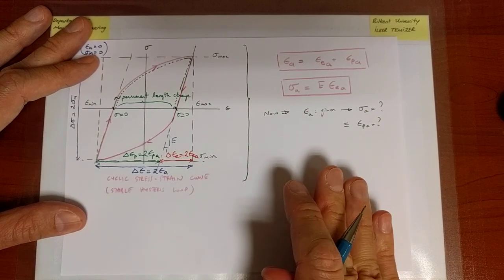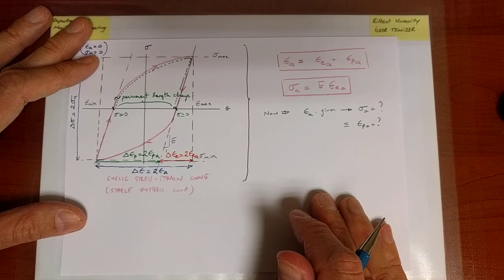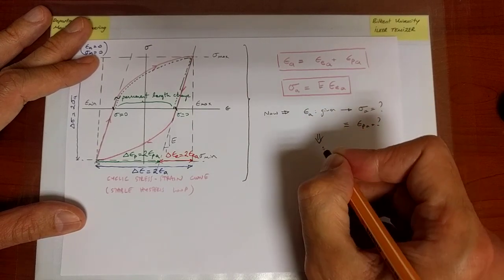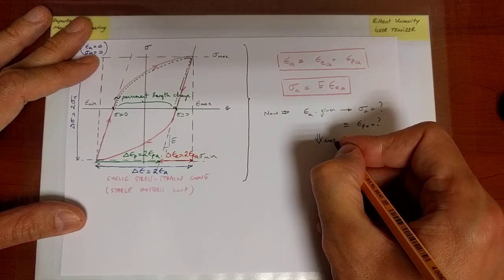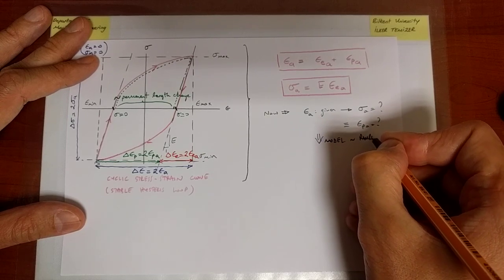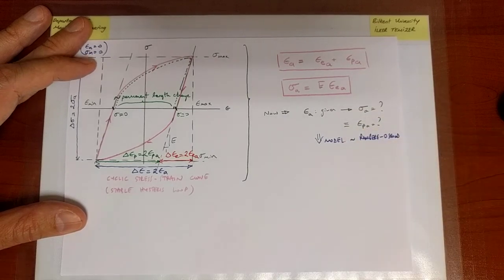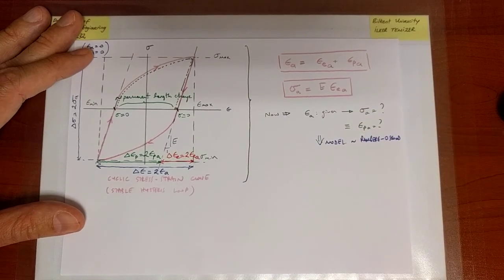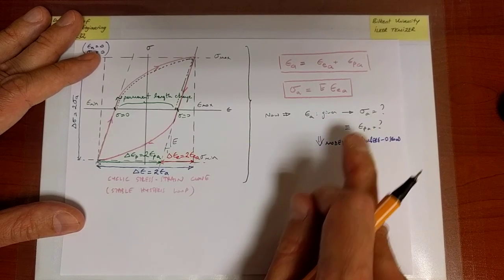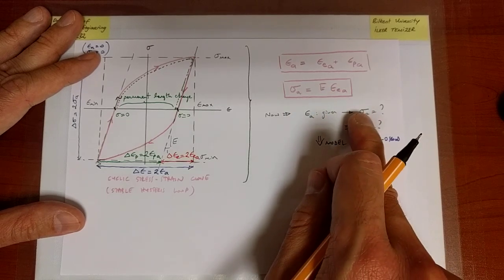And that's exactly the type of equation that we asked earlier in the context of the modeling of the stress strain curve. And in fact, we're going to now, as you will notice, follow an approach that is very similar to the Ramberg-Osgood model. So we need a model, because what we are given is the strain amplitude, and without being able to predict the plastic portion of the strain, I cannot calculate the elastic portion and hence calculate the stress.